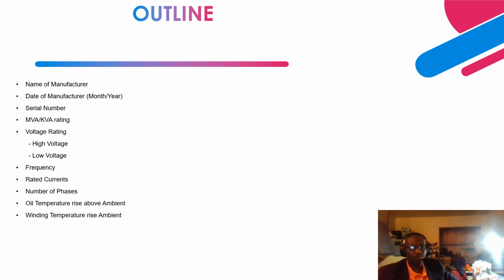That is mostly what I've seen and worked on in the industry. They step the voltage up to either 230 kV or 345 kV transmission level voltage. So the high side voltage is 345 kV or 230 kV, and the low voltage side is 13.8 kV or 18 kV, depending on the type of voltage that this transformer has.